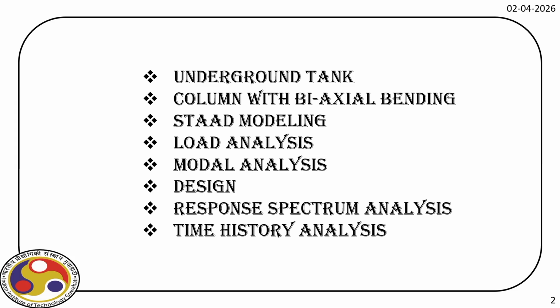Then we will revisit the design. So we'll use STAAD.Pro to design the entire building. And again, we'll follow IS 456 for this design. And we'll see what the design steps are, how we can complete the design and how we can redesign a component. Because if you recall, design is an iterative process. If one section fails, obviously we need to redesign that again. So that we'll see. Then we'll move over to response spectrum analysis.